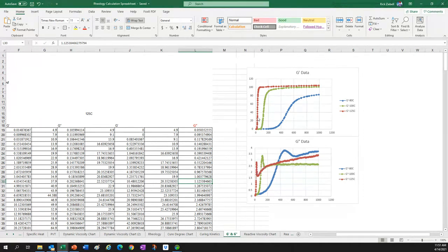If we go up here and we find 26 seconds, this gel point is 36.7%. And that's how we find the approximates, is these peaks. These changeovers indicate that the material is gelled. And so that's how we determine gel time. Not jail, like they should throw me in jail. I mean GEL, like gel in polymers.